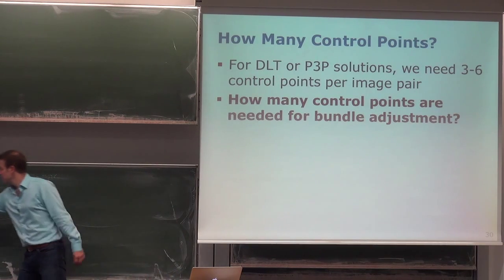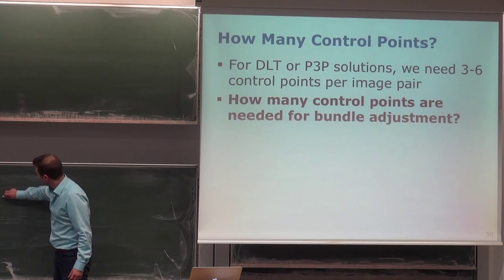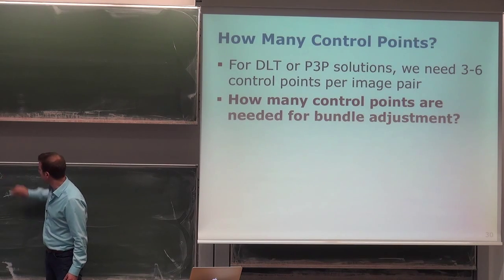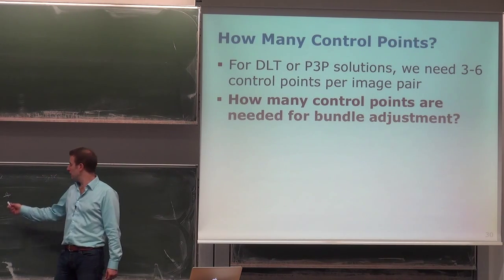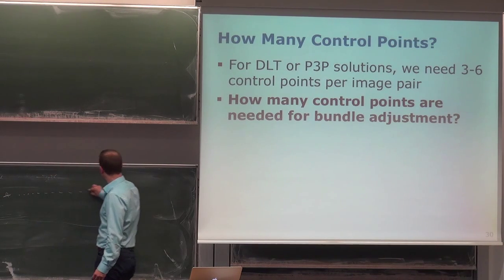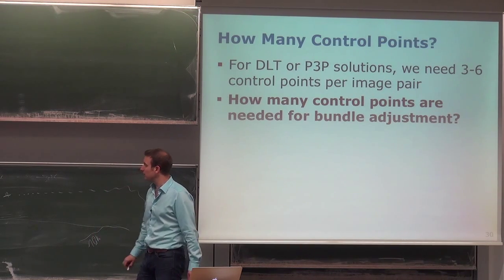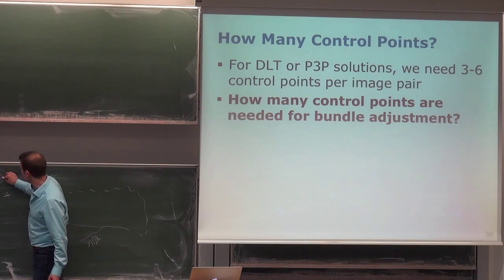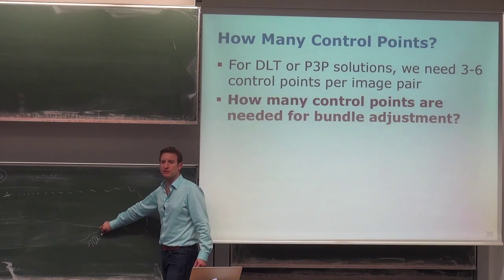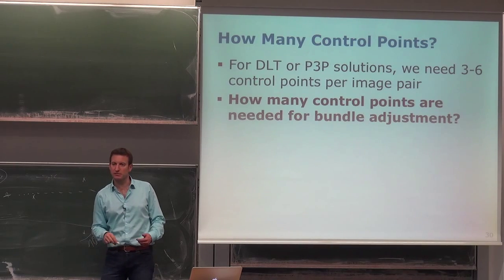So if you consider that we do the relative orientation of 2 images, let's say I have 2 camera images, one taken here, one taken here, and I have my control points, let's say somewhere over here, I can perfectly estimate that. If I start with this, do a bundle adjustment, and take a lot of camera images all over the scene, and I have whatever, 10K images recorded up to here, using only these control points over here, let's say a few more, may be highly suboptimal for getting a good estimate of those points over here. So I may want to distribute a couple of control points all over the place.